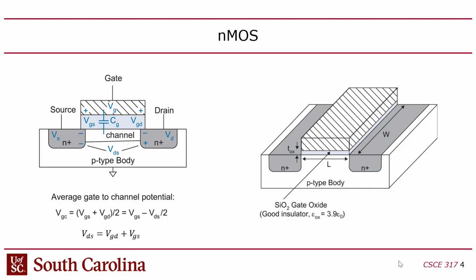So there are 2 sources of timing here, right? As I mentioned, the gate takes time to charge because it's a capacitor. You have to put a charge on this gate. That takes time. You have to get it charged up, and so that takes some time to turn on the gate. But also, once it's turned on, it also takes time for the current to traverse this channel.